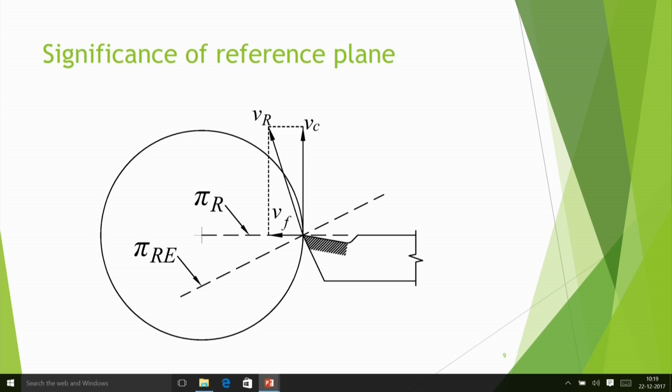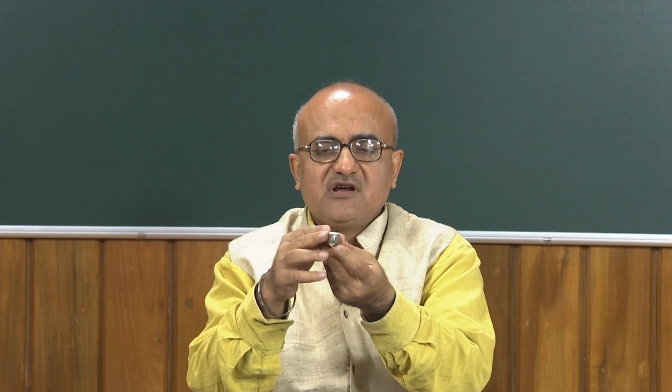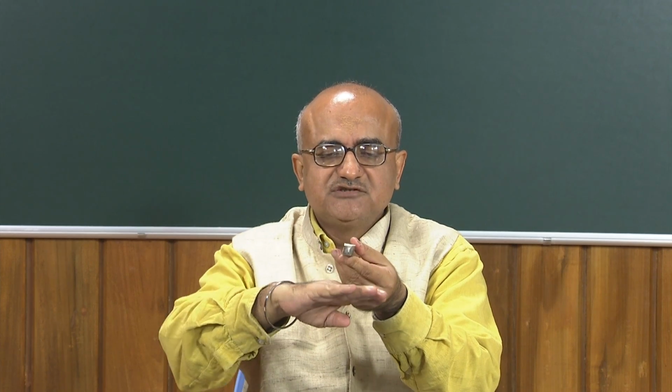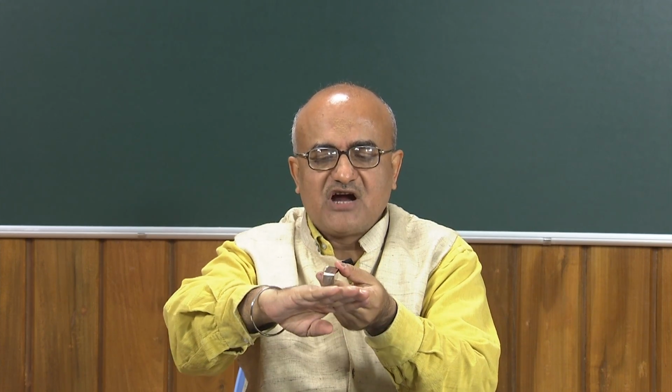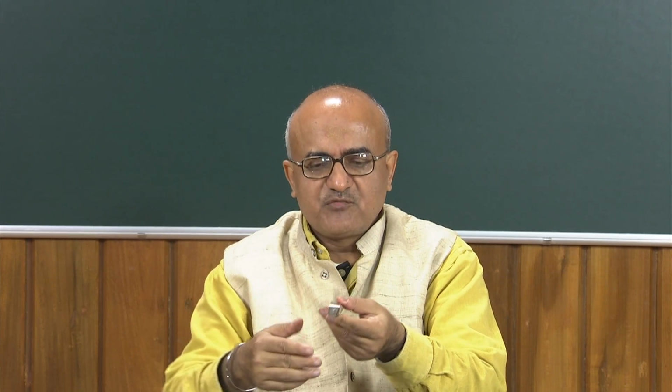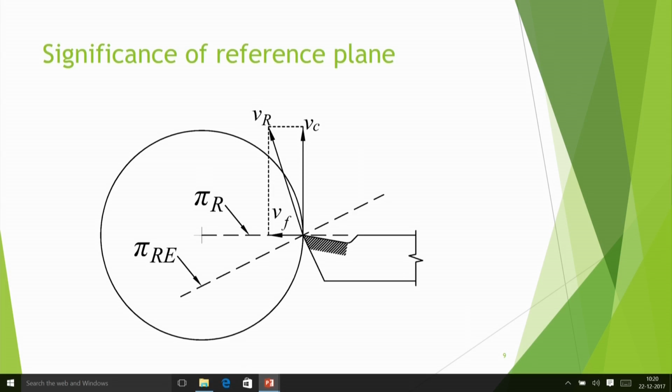That means suppose my tool is moving on the lathe machine like this, then naturally we can have this type of phenomena. Here the horizontal plane can be called the reference plane because the cutting velocity is vertical. The feed velocity is very small. That effect I am neglecting. That can always be done in this way.